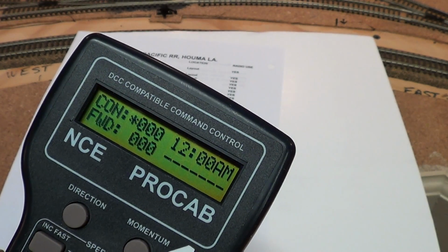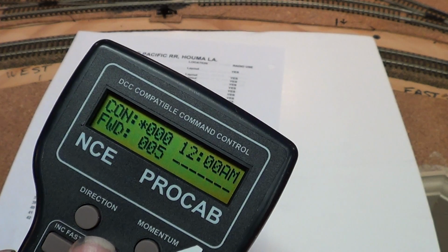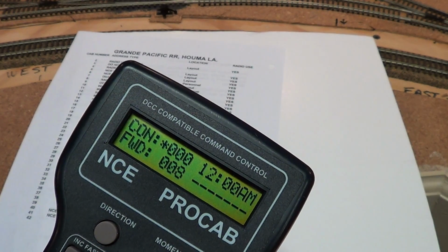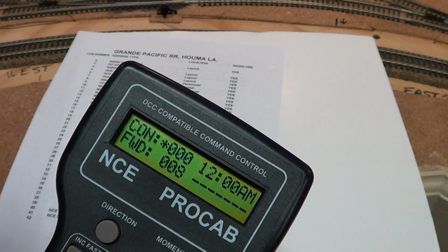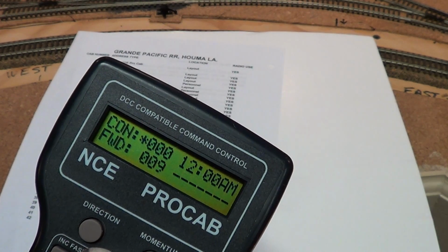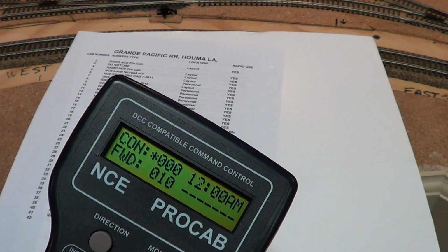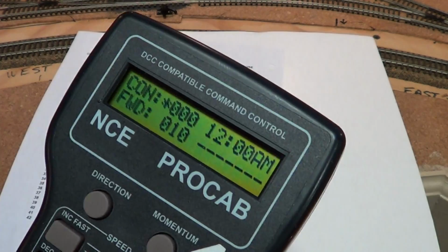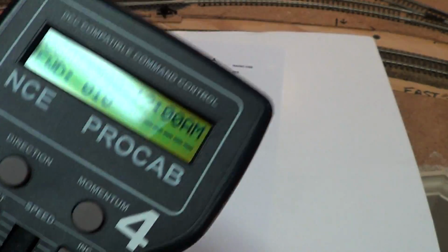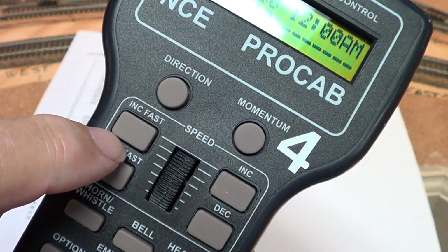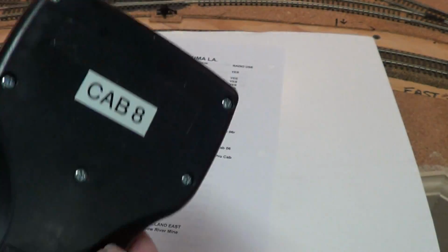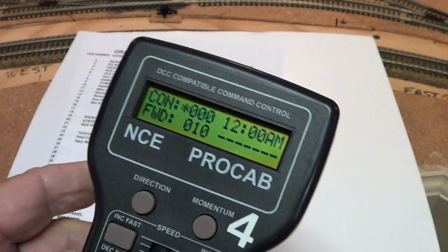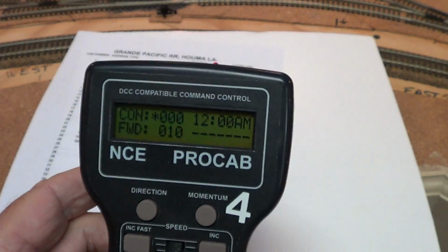You notice how when I turn this knob, the numbers go up 3, 4, 5, 6, 7. If you start rolling that knob forward and it's going up, and then it goes 3, 4, and it goes 2, 6, 7, 5, and it goes back and starts, you're turning the knob pretty consistently, and the numbers start jumping all over the place, that is a real good indication you got a problem with an encoder. That's the telltale sign that there's an issue with the encoder inside the unit. And the encoder sits right there, right behind where it says things. So if you take these screws out, you'll see it. It's right over there. See it? Not going to take this apart, sorry. We're not going into the repair issues and repair training today.